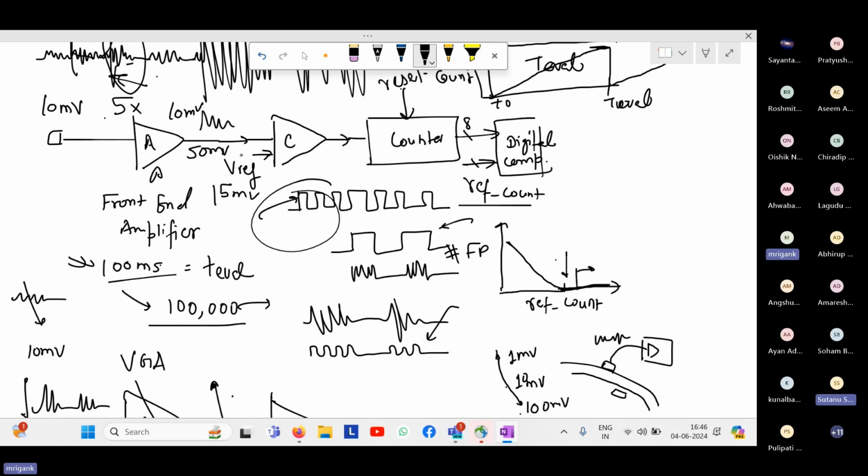The comparator offset. Sir, if we don't have the offset cancellation, then the VREF which we apply, the comparator will see a higher VREF, right? So one problem that might do is that it may increase my chance of false positive, false negative, right? Yes. So if the offset is such that it is applying a positive offset to the input, that means even if the signal is low, effectively the input will be considered as large and it will be crossing the threshold more frequently.